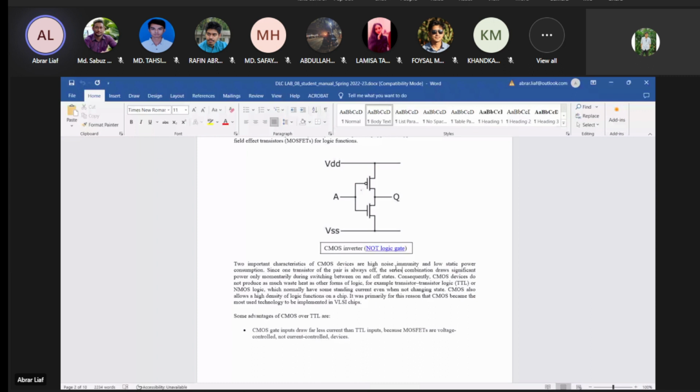That means when you are not using a particular device, for example if you leave your smartwatch unused, it will hold power for a longer period of time. The power will deplete eventually, but very slowly. Why is that? Because it has low static power consumption. It does not draw power if you do not use it. The leakage power is small. So that is one of the advantages.